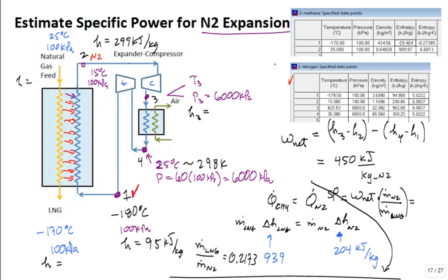What type of enhancements did we have? That's the word I'm looking for. Who said intercooler? There you go. See? Why is that going to make it more efficient? It always costs less to boost the pressure of a dense fluid. And so get it cool, keep it dense, boost the pressure. But as soon as you start to boost the pressure, the temperature goes up, it tries to expand. It makes it more expensive. So right here, this is way too hot. You know, this is coming out at, what was that temperature again?